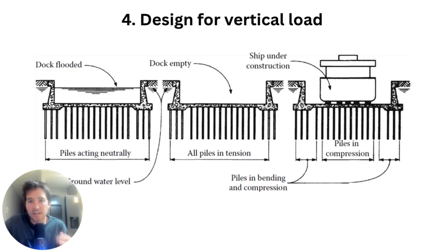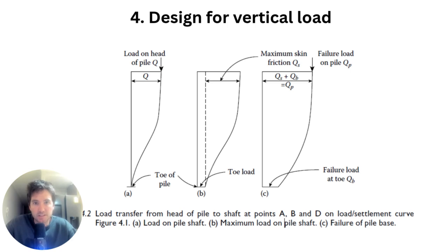So when it's in tension, there is no end bearing and you're relying fully on friction. So you can't really do what I just said before and just make an assumption about end bearing. That's only for the gravity loads. So just to highlight that sometimes piles, when they're resisting uplift, have to be in tension and will be purely on the skin friction. This sketch here shows what happens in reality for most vertical loads on a pile, in that they're taking both side friction and end bearing.